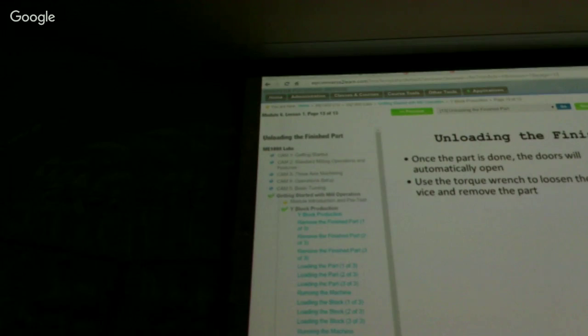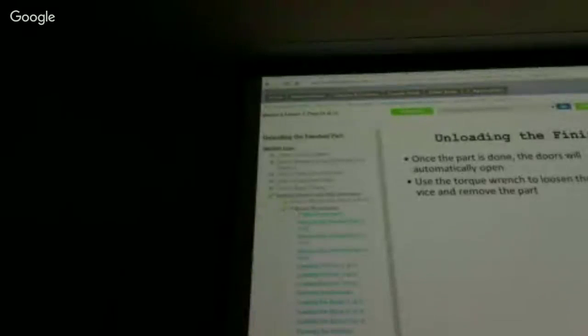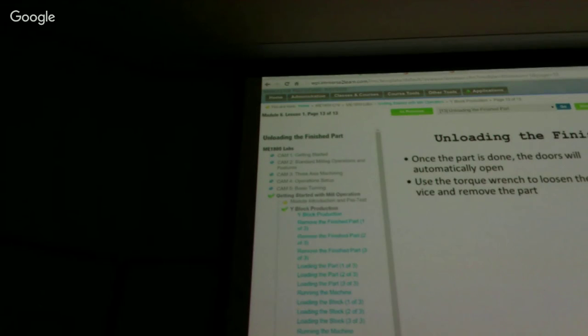Exactly. So if you're making a lot of parts that have a fillet on the outside, and sometimes you want the fillet on the outside because the marketing guy says that's what the customer demands, not just because the kid with CAD drew it that way. Sometimes you need the fillet on the outside for mechanical reasons. If you're making a lot of those parts, then you're going to get custom-made tooling that has that radius, so there's just one zip around. But you've got to have a special tool for each radius.